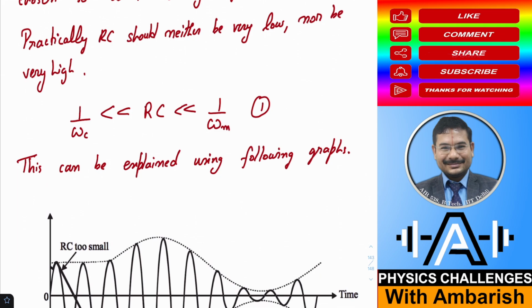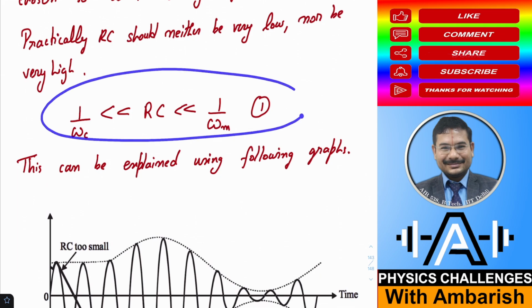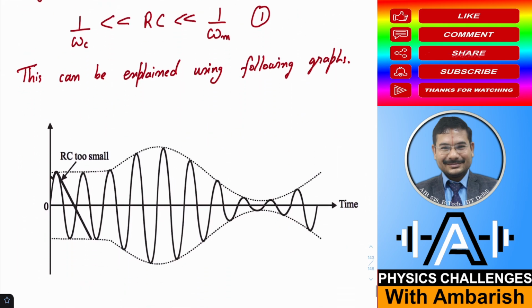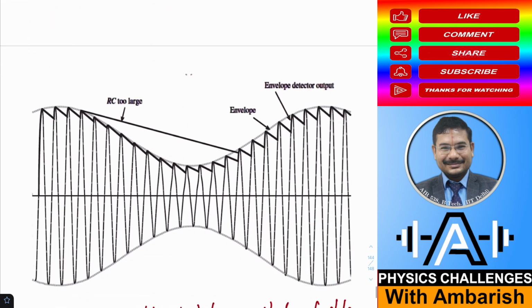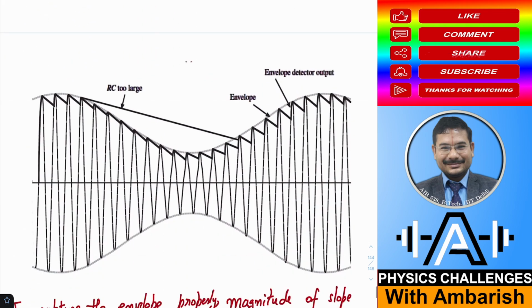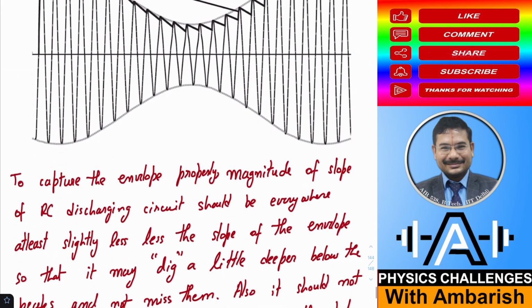But this "much smaller than" and "much greater than" sounds very vague. And in the present question we were supposed to find some good limit in terms of given parameters. How to go about doing this quantitatively, we'll see in the upcoming portion. These are the two things I told you: when RC is very small you just miss the next peak, it just discharges, and when RC is too large you are going above so many peaks and again missing so many peaks, right?